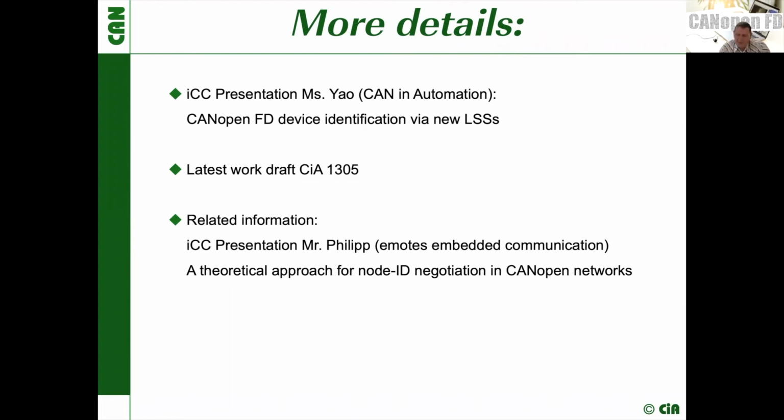The only difference is that he is using a 29-bit identifier, so that he can inform not just on a nibble basis, but about the next byte values. Therefore, he can further accelerate. The trade-off is that he has to use a 29-bit identifier instead of an 11-bit identifier.